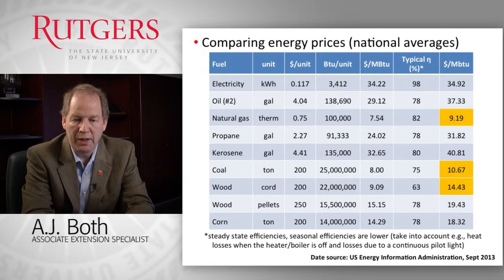So for example, for a therm of natural gas, we know that we get about 100,000 BTUs per therm from the heating system. But it also tells you the efficiency. The one but the last column shows you the conversion efficiency. So again, when you calculate your overall heating capacity, you need to take into consideration how efficiently we can convert the fuel source into heat energy before you can determine what the final boiler capacity or heater capacity needs to be.